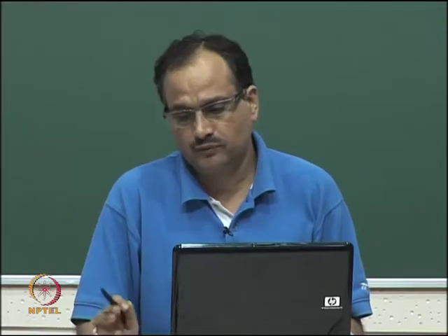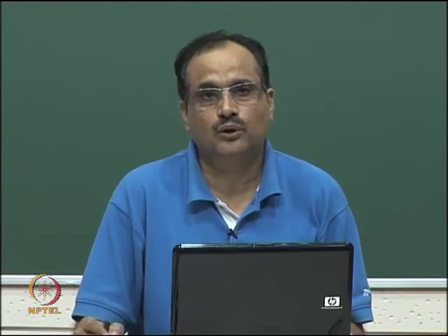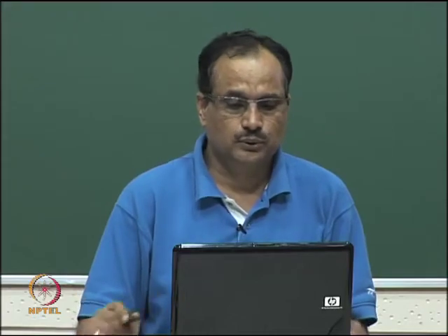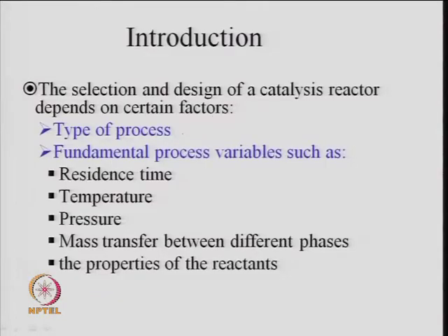That is one of the basic fundamentals, either in homogeneous reactions where you do not have a catalyst, or a heterogeneous catalytic system where the catalyst is used in the process. The reactors may be batch or continuous type. So, type of process is one. Then fundamental process variables like residence time, which is very important, when you talk about a flow reactor.